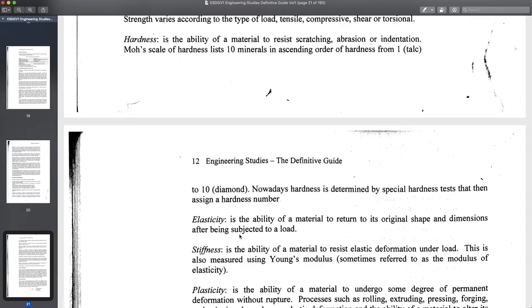Now, in our notes previously, we learned about the Mohs hardness scale. I don't even know the name of the hardness scale. Why? Because it's not relevant. You might have a science teacher who's talked about the hardness scale. You might have had a geography teacher who talked about the hardness scale. Engineers, we don't use that hardness scale. We use the Vickers hardness scale, the Rockwell hardness scale. That's what we're interested in. We're interested in nice empirical...